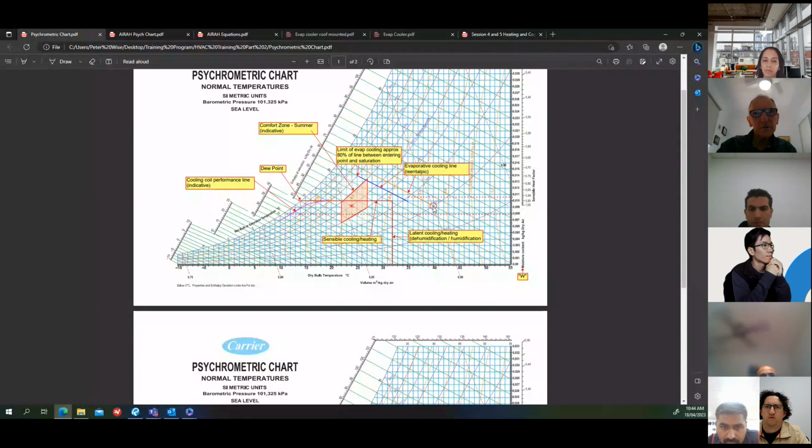So if you walk around Mildura or anywhere out in this drier country, you'll see evaporative coolers on nearly every roof of a house, because here's the potential for cooling. If you go to 80%, on a 40-degree day, you can cool the air down to 25, 26 degrees. So if you walk into a house from outside and it's 40 degrees, it's 26 inside.